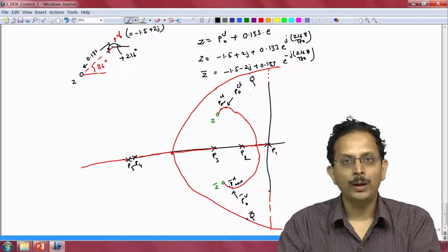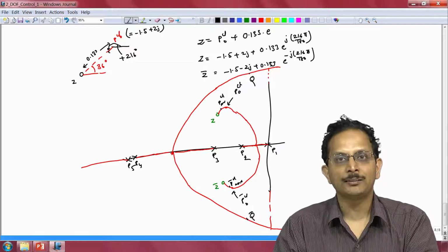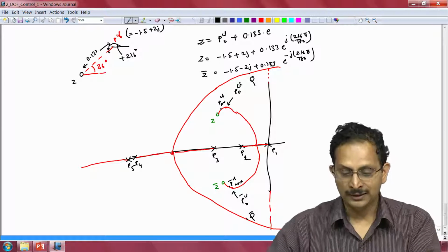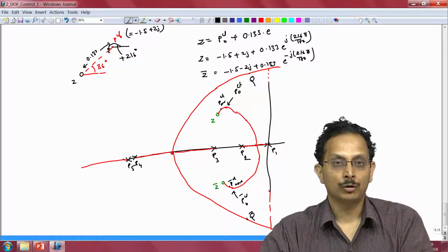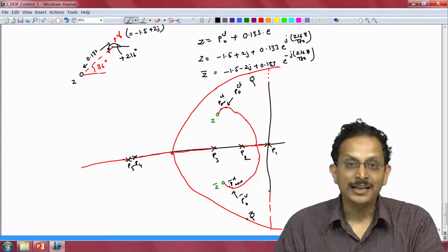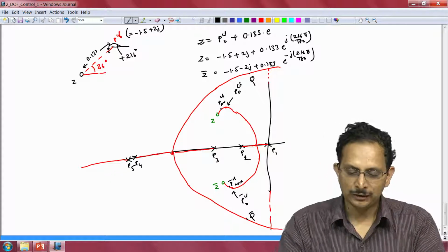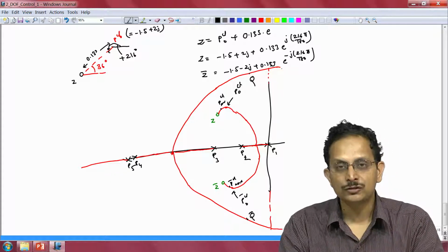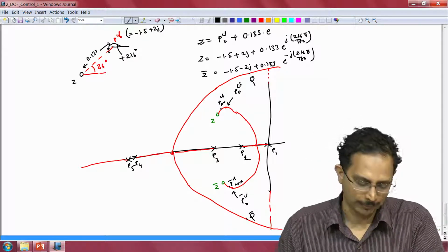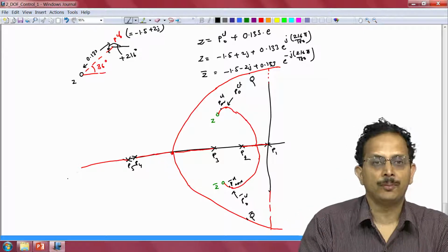So we would have one pair of poles on the branch that emanates from P4 and the other branch that emanates from P3 and breaks off towards the imaginary axis, and these two closed loop poles are not guaranteed to be stable, because it is very likely that when the plant assumes its maximum gain possible, the point Q is on the right half of the complex plane, and thus our closed loop system might become unstable.